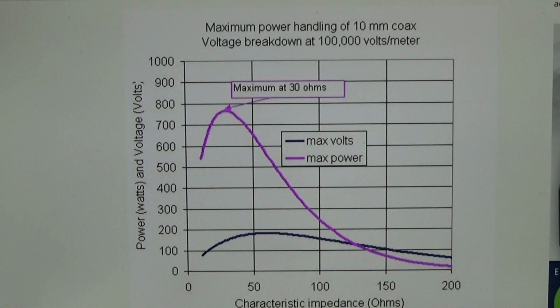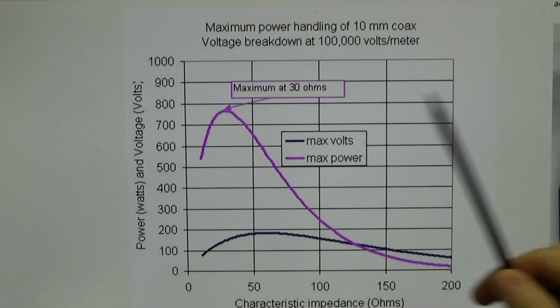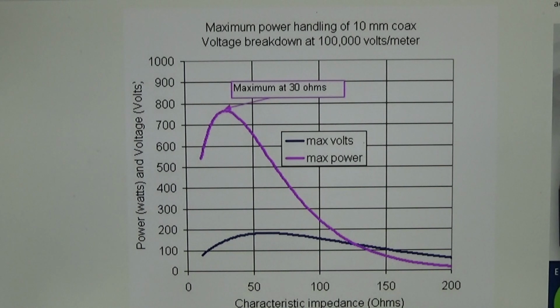So now we are a little bit in a problem. For the receiver, we know we should have 75 ohm, because then we have the lowest loss, and that is brilliant. But on the other hand, we can't use our 75 ohm broadcast coax cable, as 75 ohm is not really able to handle high power.